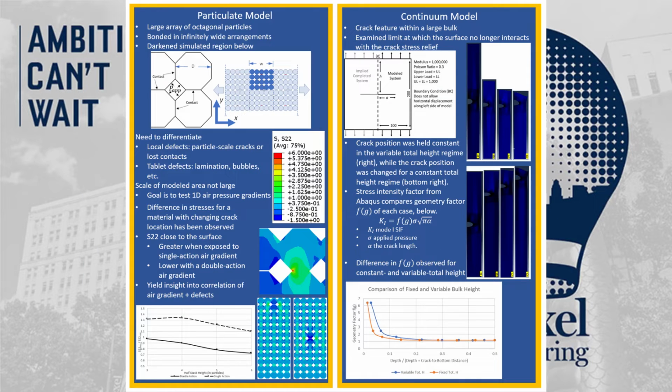We developed a particulate model in ABAQUS 2021 where an array of highly ordered particles were arranged with interparticle pressure. The interparticle pressure was discretized according to single action and double action pressure gradients as developed in Zavaliangos 2017 and Klinzing 2019. Using this approach, we were able to examine the local vertical stress on a contact adjacent to the crack, indicating a crack's propensity to grow and disturb the adjacent contact.